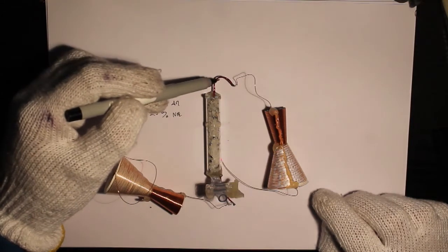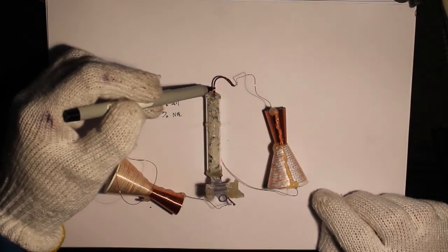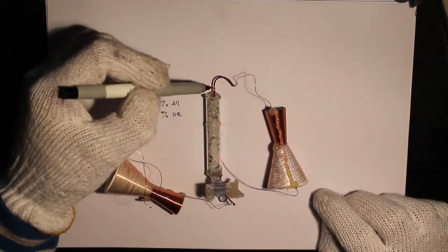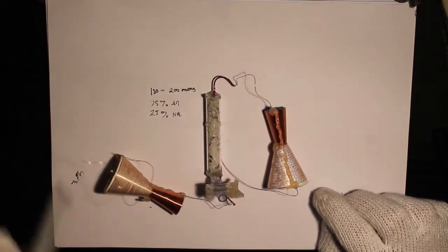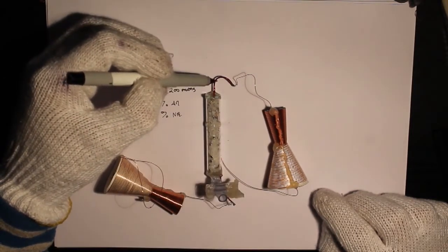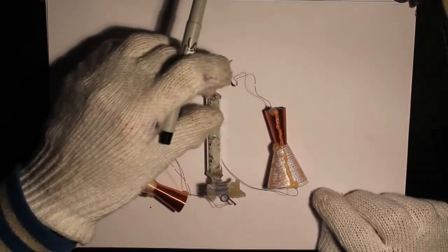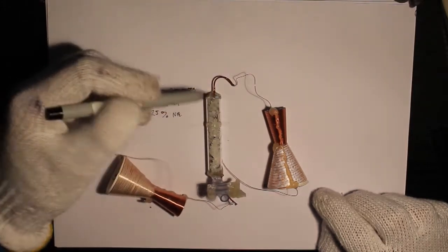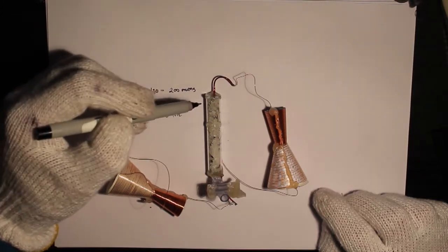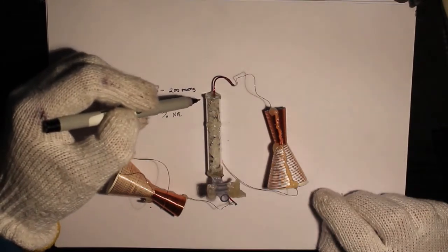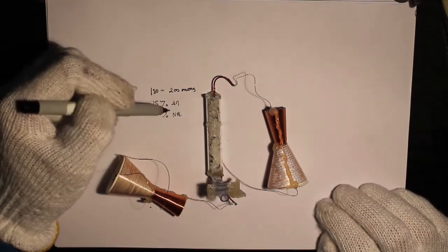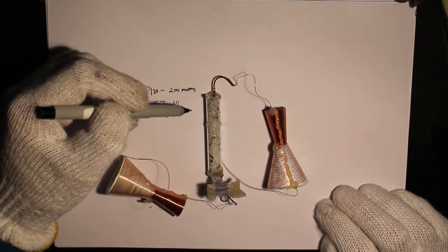This wire is insulated. I said it was supposed to be, but it's probably better if it's bare. It has to be insulated around the coils, but it's probably better if, up close to the tube, it's bare. So basically, that's the tube: salt, mercury, a 150 to 200 micron vacuum, and 99.99% argon and neon remainder inside.